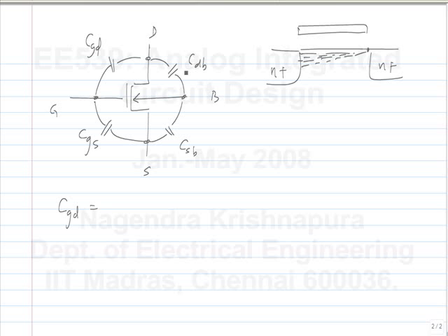But there will be the overlap part of it. It will just be the overlap capacitance. So how does it depend on the size of the device? It changes only with W, right? Because W is the dimension into the page here, and if you go further into the page, you have more capacitance. So CGDO is the capacitance per unit length.